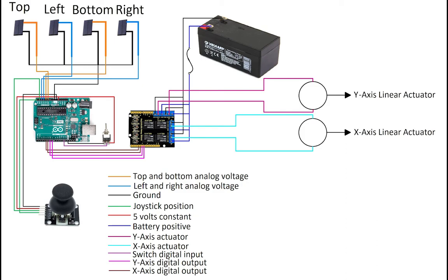When the corresponding pin is written high, the respective relay common switches from normally closed to normally open. The relay board works as follows. Pins 4 to 7 control relays 1 to 4 respectively. That being said, pin 4 is relay 1, 5 is 2, 6 is 3, and 7 is 4. The actuators are connected to common because depending on which relay is active, that will dictate the direction of the linear actuator travel. Since this project is using 12 volt actuators, we must use relays and an external power source to operate the linear actuators.